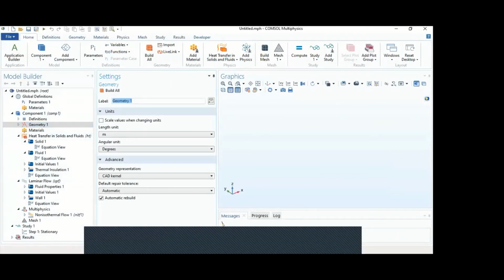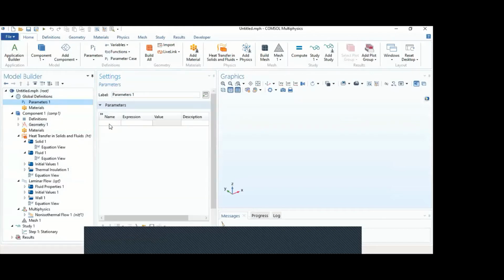In the parameters, I'm going to set up some parameters. So I'm going to set up the temperature of the cold side, let's say T_c is going to be 300 Kelvin. By typing the unit between square brackets, I do not need to convert it from Kelvin to Celsius or the other way around. I'm just going to type the unit I use between square brackets, and it's going to be automatically converted. And T_hot, T_h, to be 330